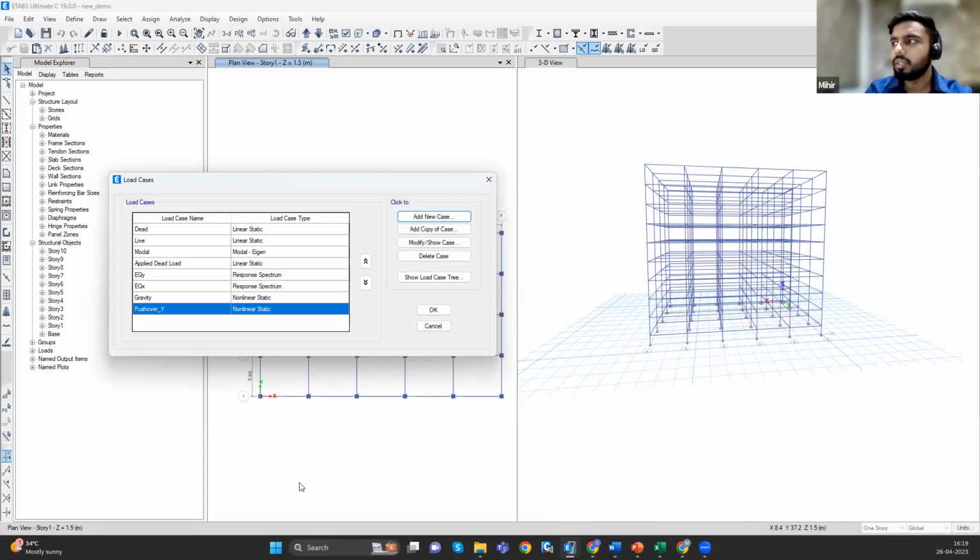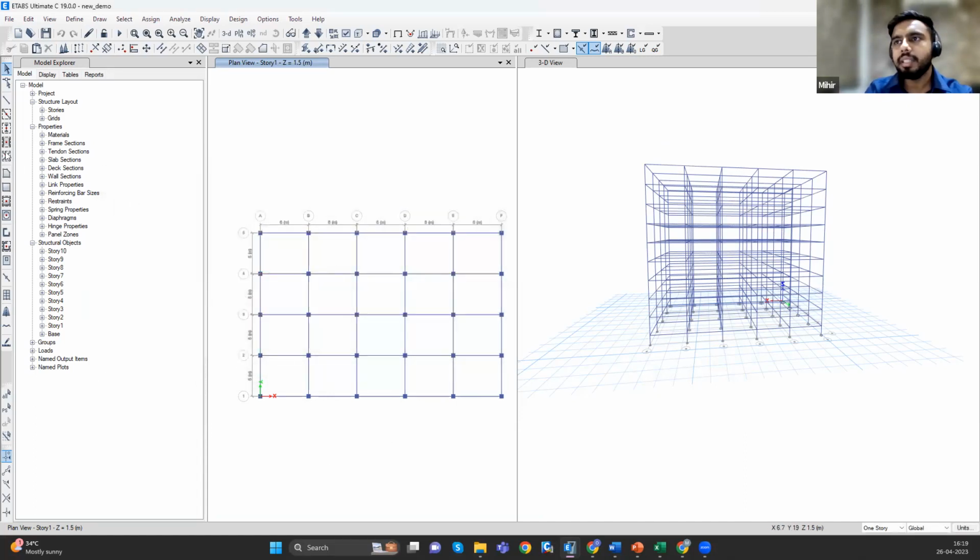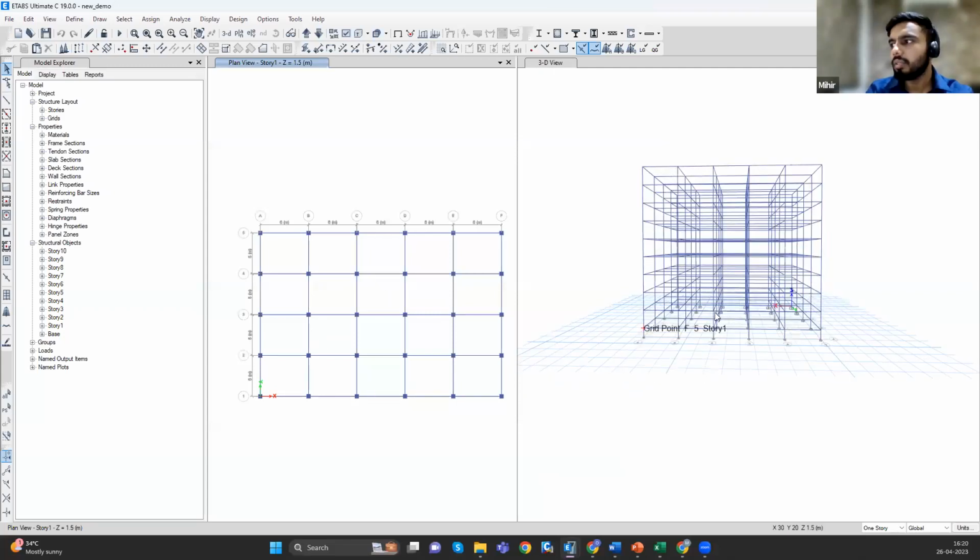We just need to ensure that from the modeling perspective, all the definitions are done correctly and all the standard loads are applied. You can change the section properties, but in case 520 members are failing, you need to check how the forces are also applied. There might be some problem with that because in my case, as I mentioned, this story was failing. And I believe that is because of the response spectrum function forces that have been applied. So we can check with that.